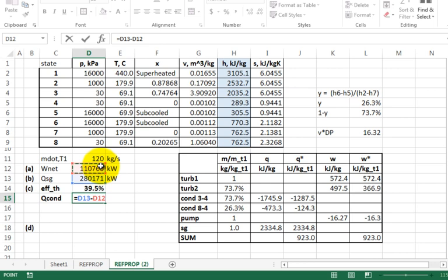Or do a global energy balance for the plant. I've got some coming in the boiler. Energy either goes out as work, out the shaft to drive the generator and make electricity, or I have to reject some to the environment. Isn't that it, in kilowatts? Isn't that nearly 60% of what came in? That's another way of calculating it. You could say 1 minus the efficiency times what came in.